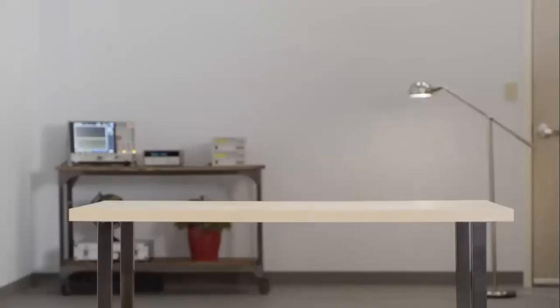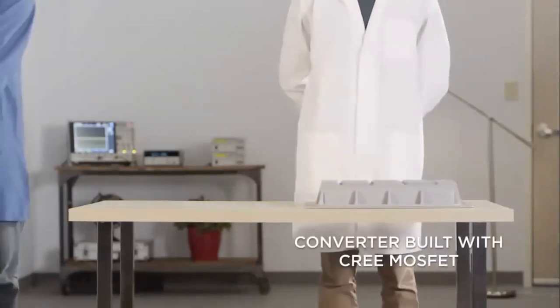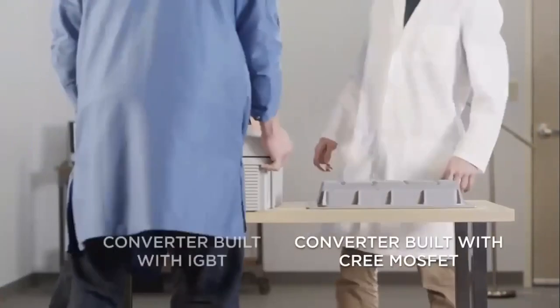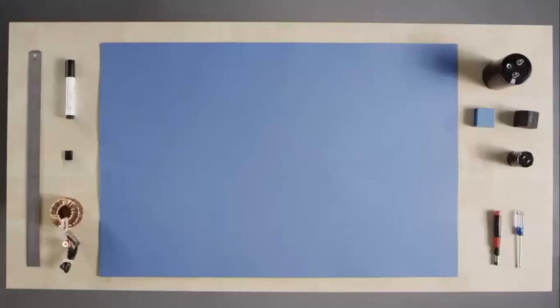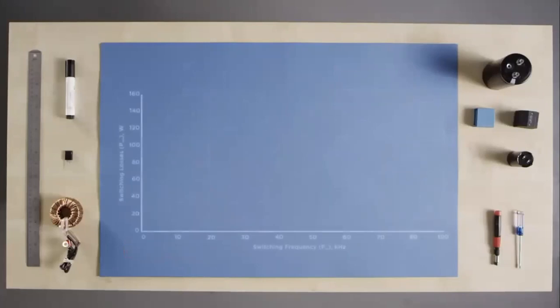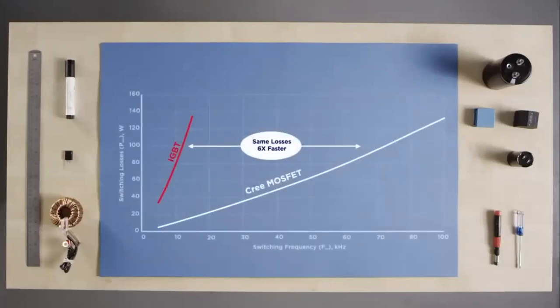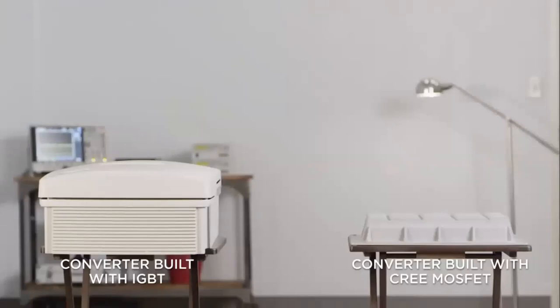Not convinced? Let's see an example application. Here's a 10 kilowatt power converter built with a Cree MOSFET. And here's one built with an IGBT. Did you spot the difference? So to recap, an IGBT has 6 times higher switching losses than the Cree MOSFET. This requires designers to switch them slower or use more of them. Both options are costly and produce larger systems. With the Cree MOSFET, you pay a bit more for the actual MOSFET, but you save a lot of money at the system level. The end result is a product that is cooler, smaller, and better.